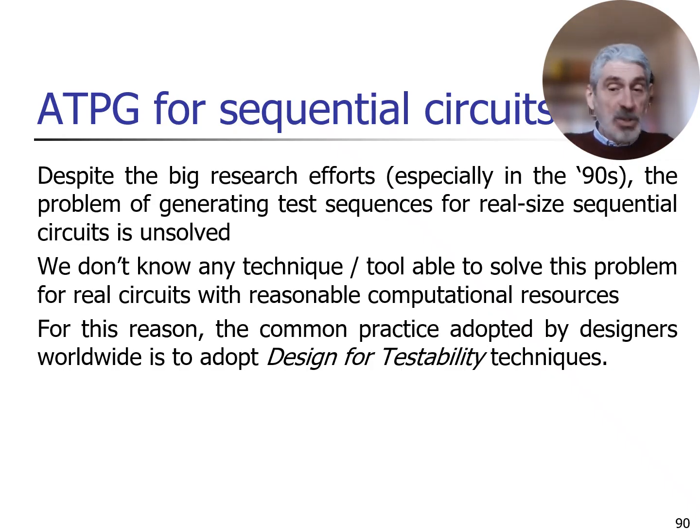Since we cannot test sequential circuits, we should introduce a test mode different than the normal mode, so that when we enter the test mode, we will force our circuit to become a combinational one from a test point of view. And in this way, we can test it because we know how to test a combinational circuit. Okay? This technique, which is called scan, we will comment on and introduce in a moment, is the first design for testability technique to be introduced. It is very popular, together with the other design for testability technique, which is called BIST, the built-in self-test. And I think it is worth commenting on it a little bit.